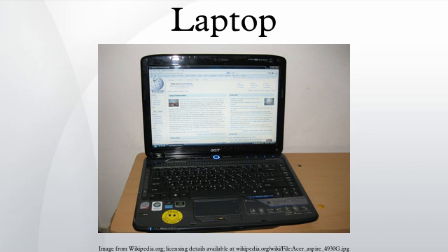Waste heat is usually exhausted away from the device operator, towards the rear or sides of the device. Multiple air intake paths are used since some intakes can be blocked, such as when the device is placed on a soft conforming surface like a chair cushion. It is believed that some designs with metal cases, like Apple's aluminum MacBook Pro and MacBook Air, also employ the case of the machine as a gigantic heat sink, allowing it to supplement cooling by dissipating heat out of the